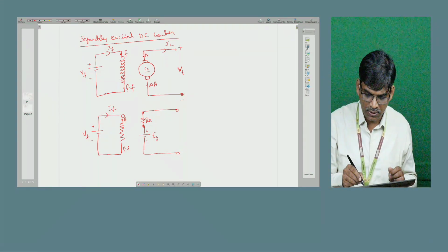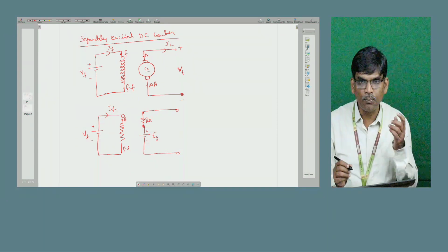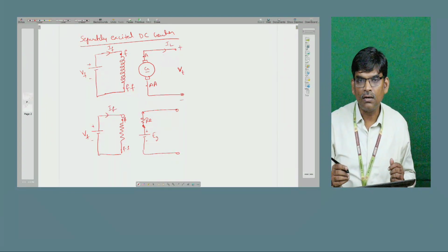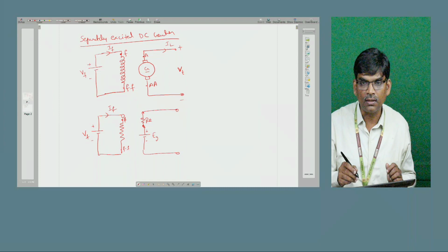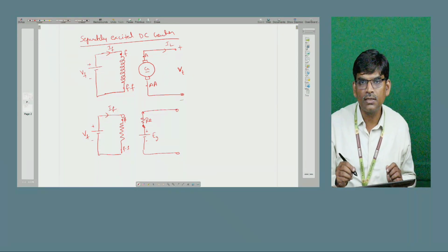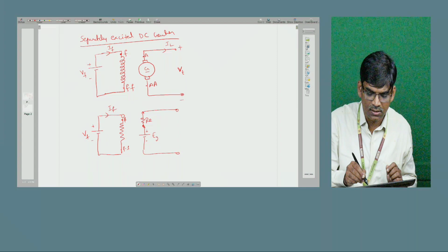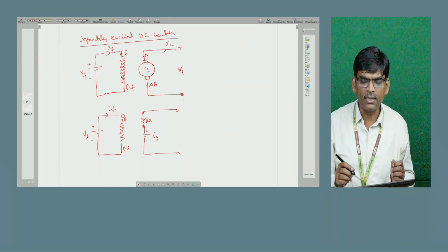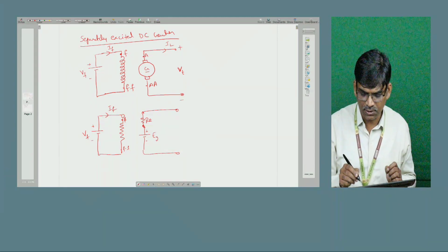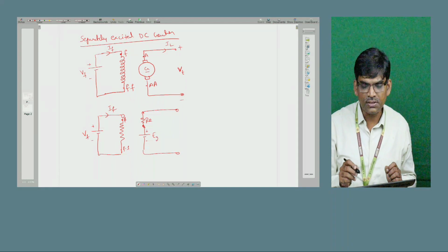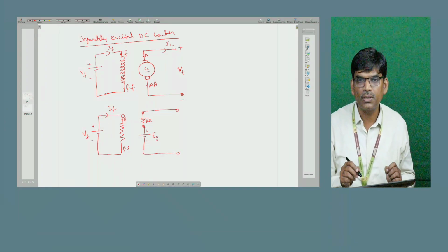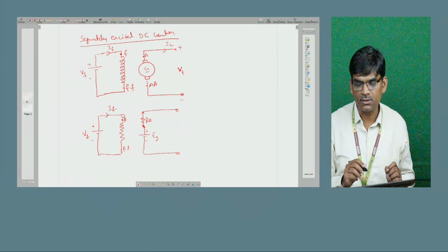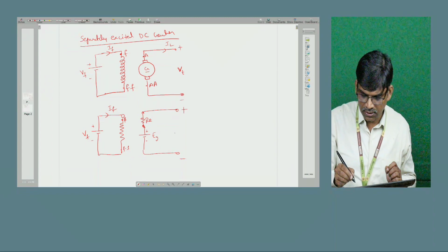Simple in circuit, the entire RA is the lumped resistance, a combination of the series field, compensating winding, and interpoles winding. It can simply be represented as RA. Also here the brushes are there. Brushes also offer some resistance, maybe very little. That's why sometimes we show a small battery in reverse of the actual induced voltage, or otherwise you can consider it in the resistance. That's what RA is: the lumped resistance of all the series windings of this armature winding, including armature resistance. Now you can take it as the terminal voltage.